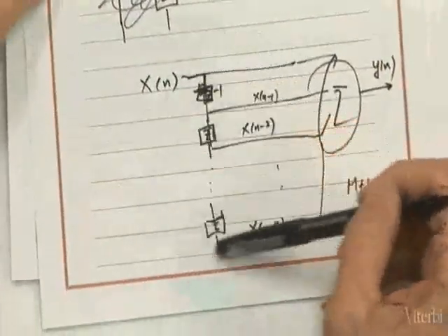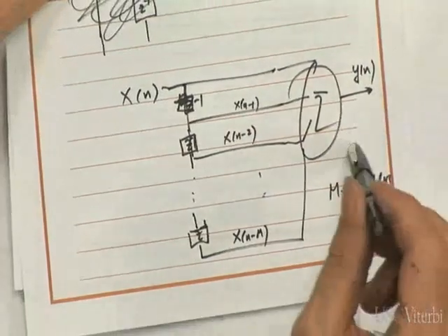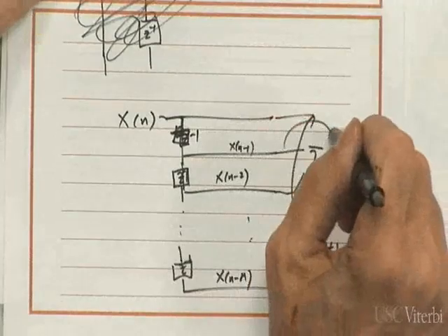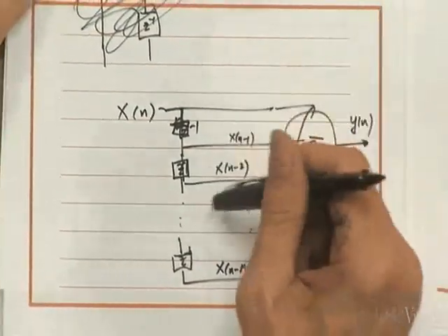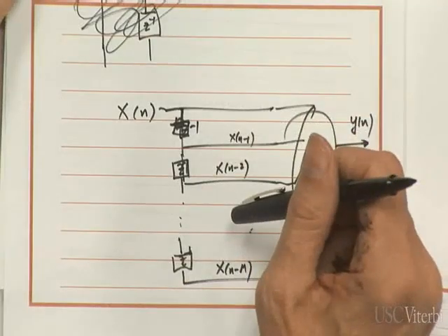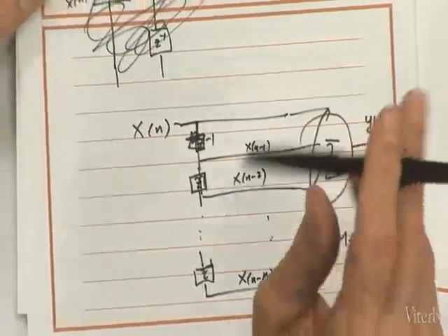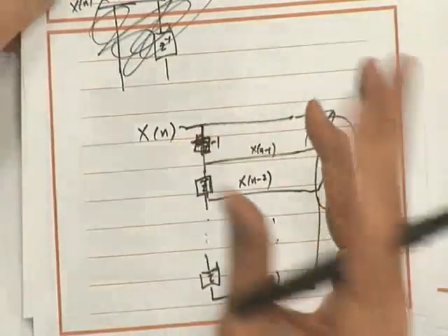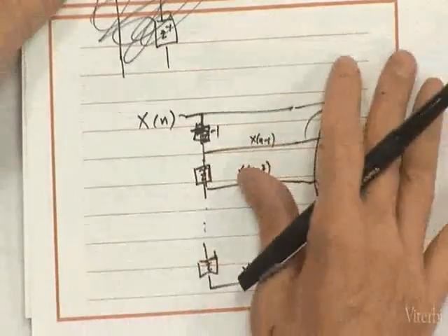So you mean say here you have a time series that you want to filter, and you have to define a window size, and that size is m, right? So in order to get the first filtered point, you need m samples. That's correct. So you will incur a delay.